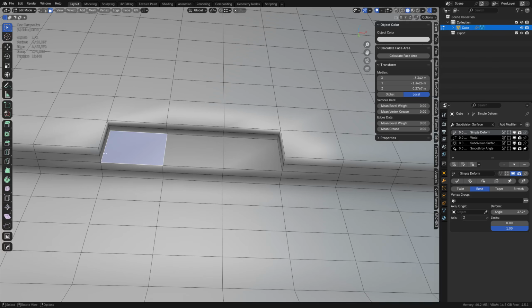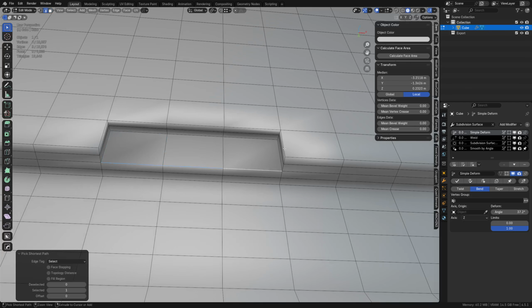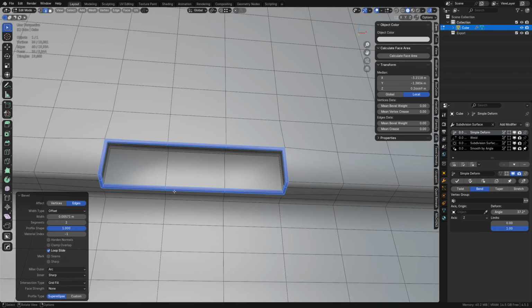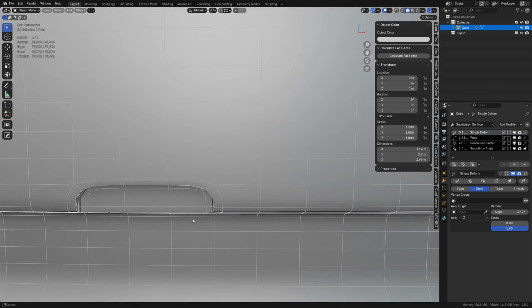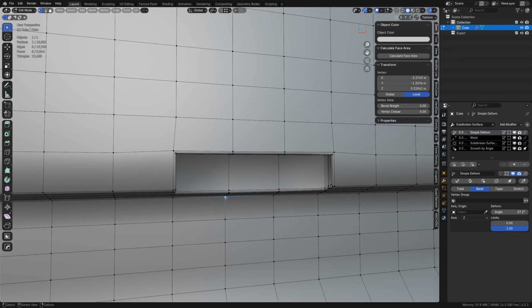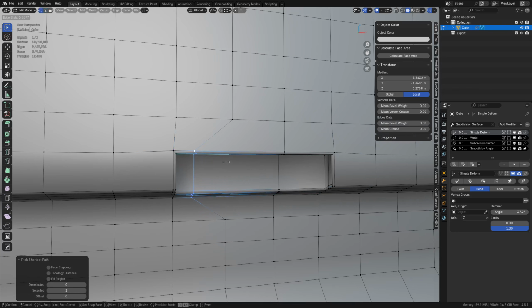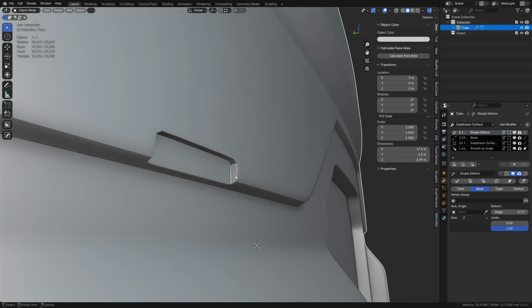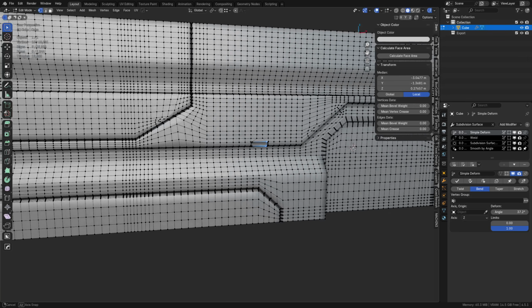But this can be kind of problematic because we could use creases, but at this point, you're better off switching to just regular subdivision with holding edges. Right? Change the profile to 1. And now, anytime you need anything to be held in a certain shape in here, you want to try to get it to a high enough resolution where it's not too crazy to work with, but you can also shift things around if needed. And it might create a little bit of a flat spot when it bends out, but it shouldn't be too bad, like not very noticeable anyways.